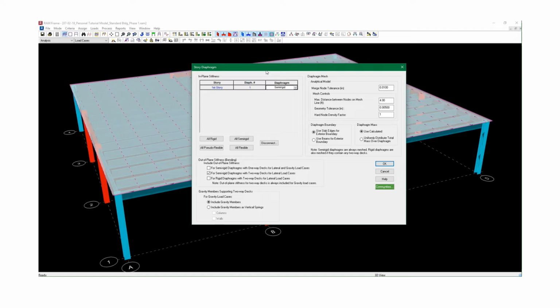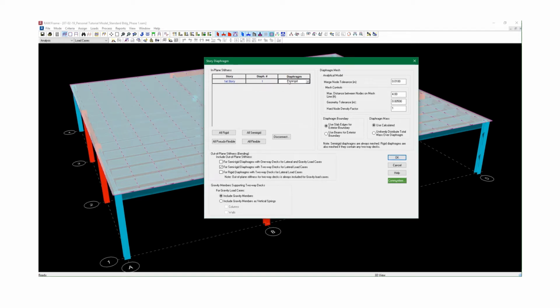And this is actually something you need to pay attention to, because when it's semi-rigid, the values that you use in RAM Modeler for your Young's modulus actually will affect your structure. It will affect the results of your structure and the analysis, and whether you get warnings and things of that nature. And I'll show you that in a minute.